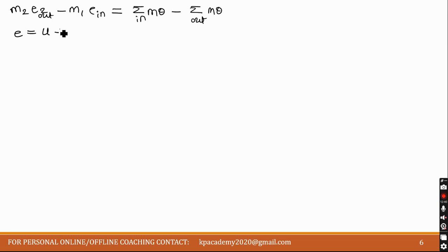So it is equal to U, that is internal energy, plus kinetic energy plus potential energy for non-flowing fluid inside the tank, right? Inside the tank, whatever the fluid is there, in this case we have air, so for that we have this E, that is internal energy, kinetic energy of that fluid and potential energy of that fluid, right? Now in this case we are ignoring the kinetic energy and potential energy, so this becomes zero, this also becomes zero.